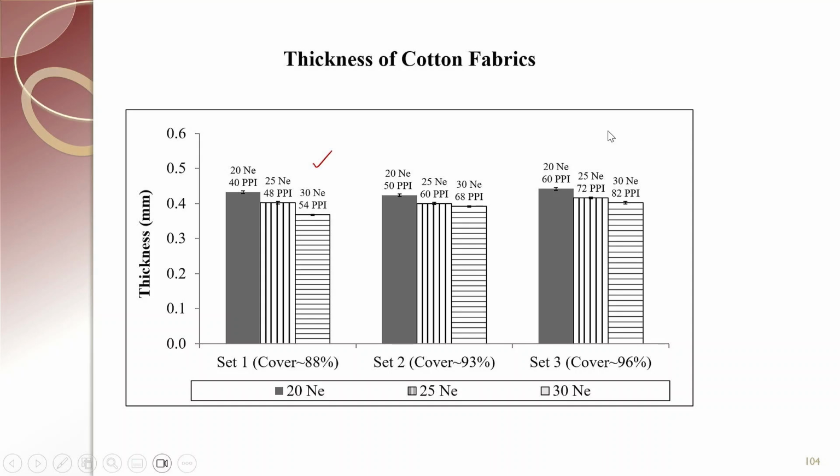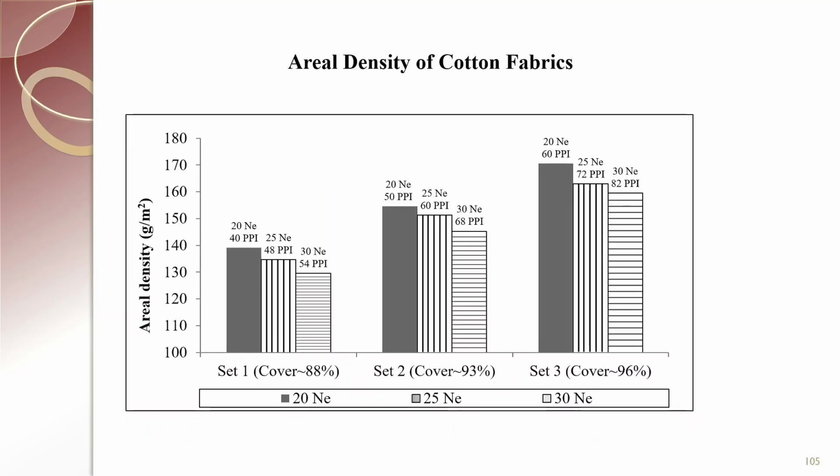Here the cover factor is 88%, 93% and 96%. The areal density is showing the same trend. Areal density reduces as the yarn becomes finer.